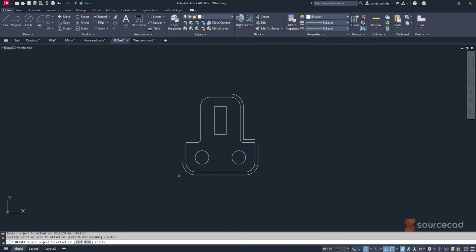Now in this case, this offset is made using broken segments because, well, our drawing is exploded. But what if we just join our entire drawing? In that case, we'll get one single segment, and this type of gap will be merged as well. So let's just delete it all, and now let's go to join. So modify, join, and I'll select this entire geometry.